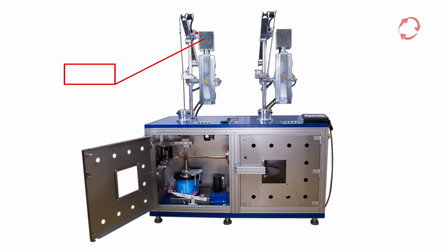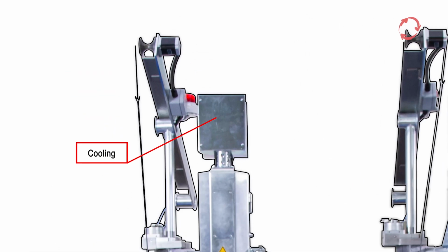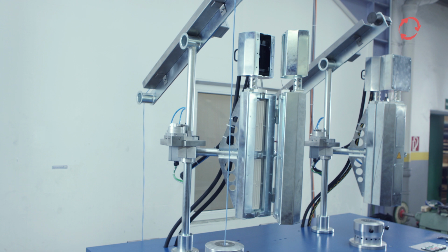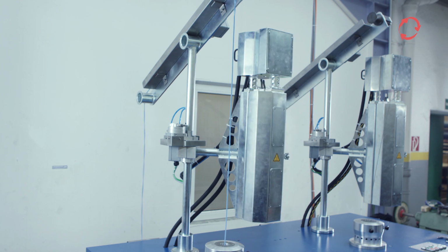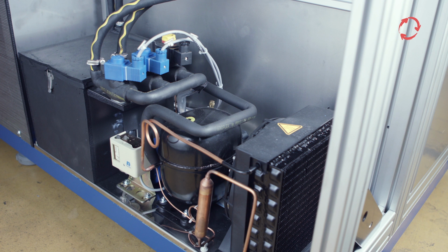The cooling unit is located above in a two-section housing, integrated into the two-part heater housing. The spirals moving up out of the heater are cooled back down in the cooling unit in order to compress them, and to allow for spirals to be manufactured from thick monofilament. Cooling occurs via the cooling unit installed on the back side of the machine.